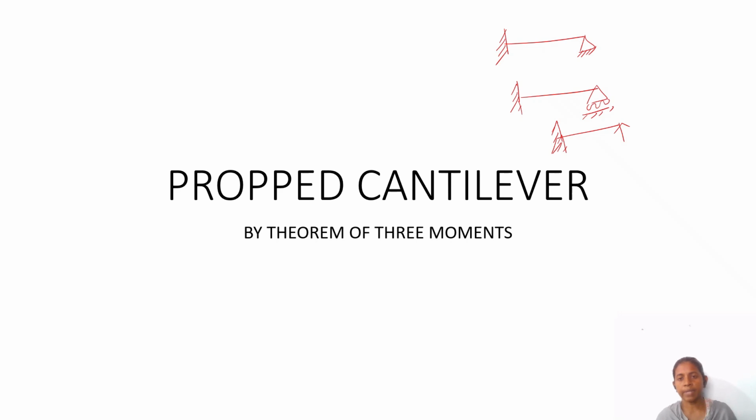There are many analyses for finding the deflection, bending moment, and shear force of propped cantilever. A very simple method is the theorem of three moments. Already we have familiarized with the analysis of beams of two spans using the theorem of three moments. For the theorem of three moments, we need at least two spans so that our equation can be written with the MA, MB and MC components.